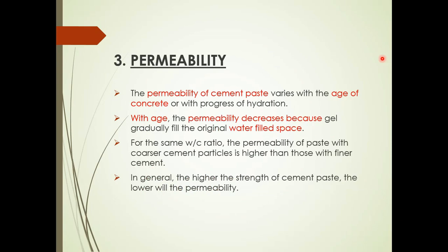The permeability of the cement paste actually varies with the age of the concrete, or with the progress of hydration. With age, the permeability will decrease because gel gradually fills the original water-filled space, so we reduce the voids. For the same water-cement ratio, the permeability of paste with coarser cement particles is higher compared to those with finer cement. That is why we need to use finer cement to get better durability. In general, the higher the strength of the cement paste, the lower the permeability.